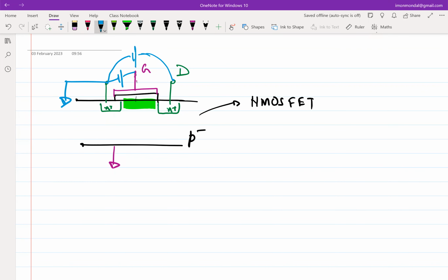Okay, so let's assume for the time being that this junction is forward biased. Maybe you were not careful enough. You had a battery where you had given a positive potential to the P-type during design. This is in your control. So now, because of that, what will happen? This junction becomes forward biased, or can likely become forward biased. If it becomes forward biased, then the carriers will flow directly from the body to the channel to this, right? So this entire current flow loop will now become this through the body and back.